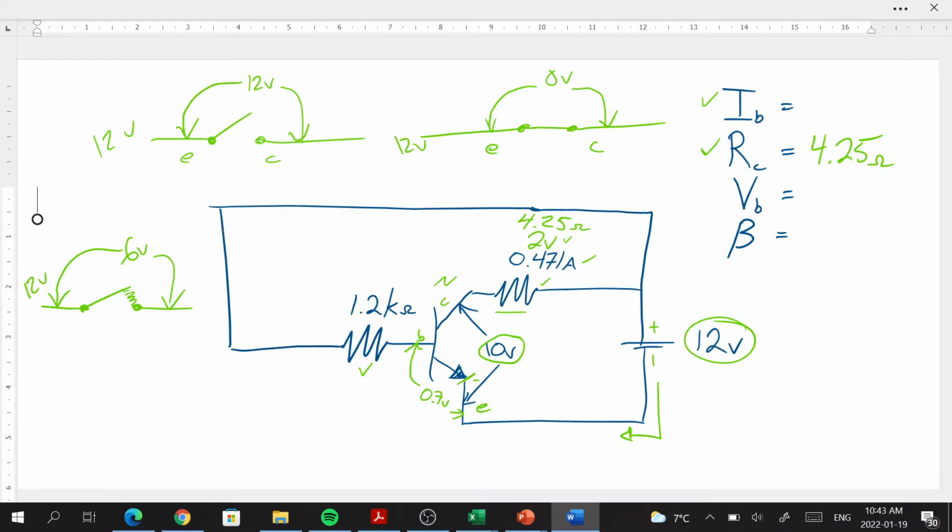And that's because a transistor is made up of diodes, pretty much. So to trigger a forward bias diode, you need a potential of over 0.7 volts, assuming that transistor is a silicon transistor. That diode is a silicon diode. So once you get the 0.7 volts, well, we know that this drop between the emitter and the base is in series with the resistor on the base. And so they need to equate to the 12 volts as well.